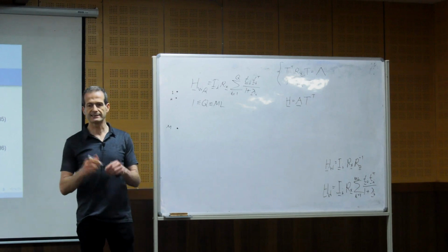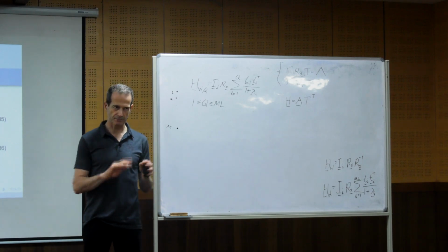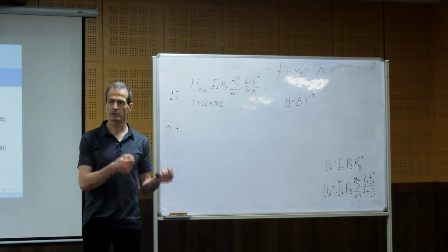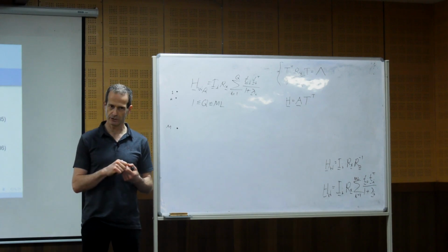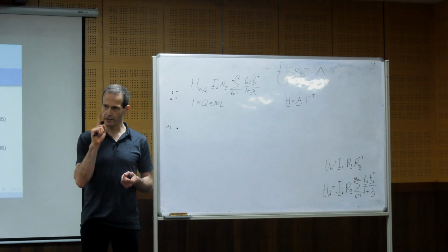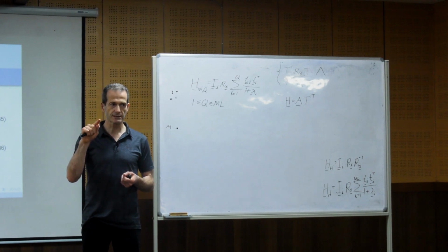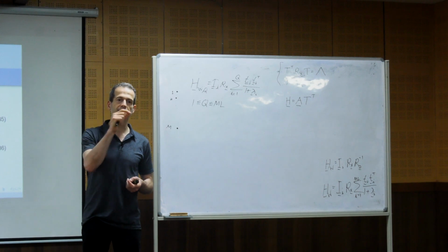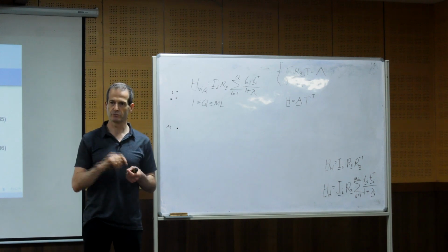Now, in the signal-plus-noise subspace, we want to reduce noise. Of course, it will come at the cost of increasing the signal distortion. The smart way is to reduce in such a way that you pay the least amount of distortion for noise reduction.